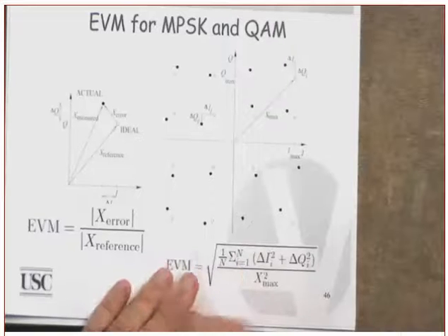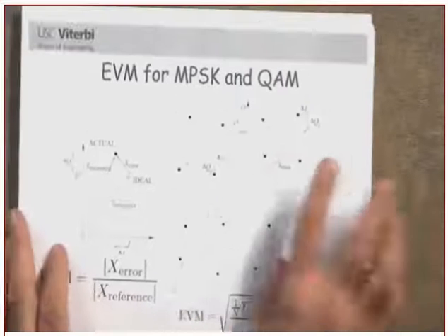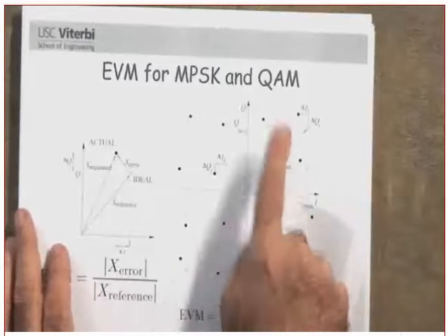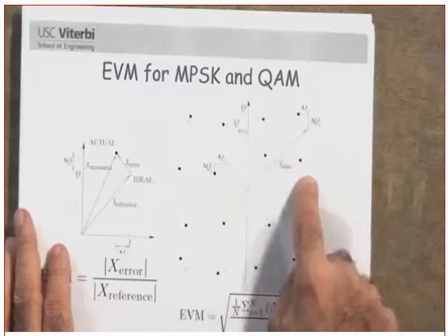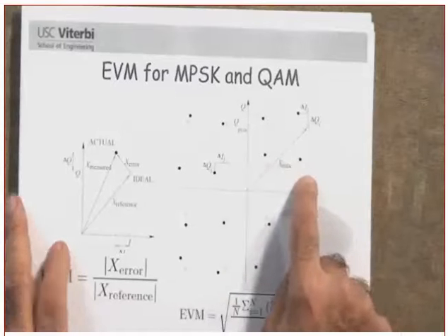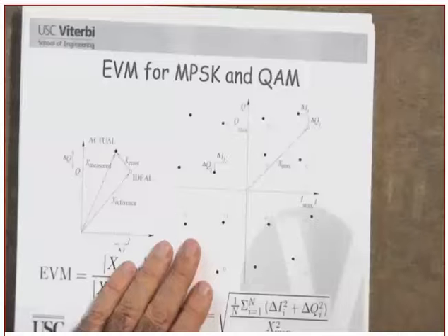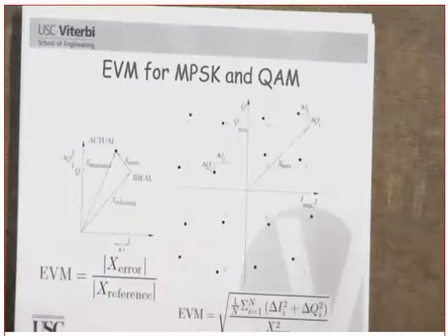But in any case, in here, what is this, by the way? Is this MPSK or a QAM? QAM. Why is it QAM? Because you can see that the amplitude and the phase are changing. When you do your simulation, and the question asks you to simulate QAM, you need to calculate the average energy, because the energy is going to change. Did you get my point or not?